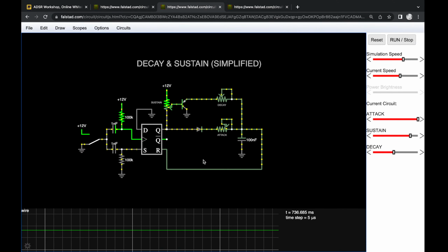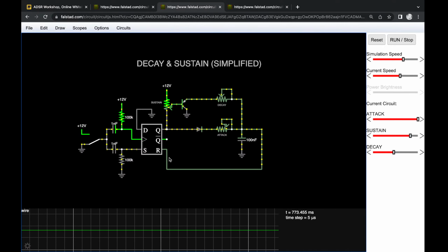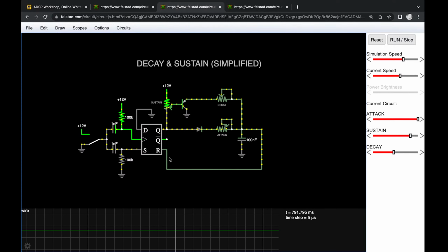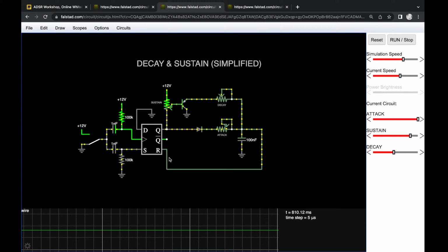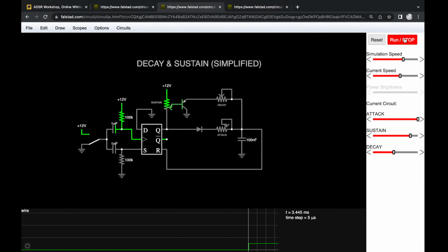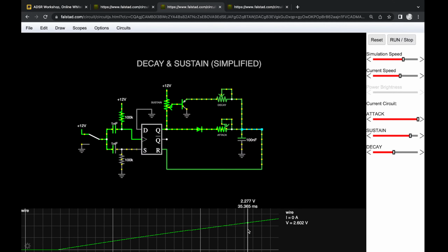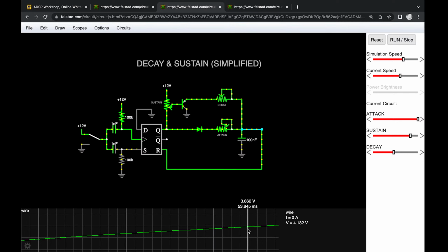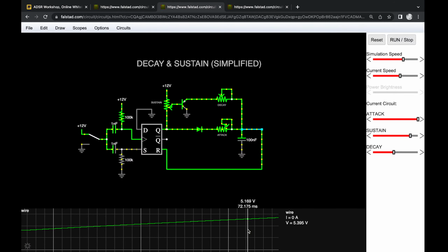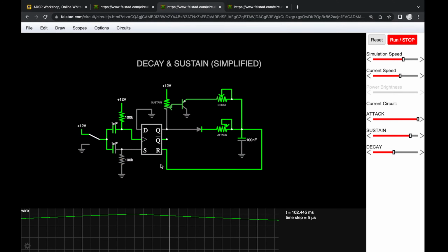Also, I said in the beginning that normally a Eurorack ADSR will peak at around 8 volts. So we should make sure that it does that, because at the moment our envelope peaks at 6 volts. If we try this again, boom, yes, it's 6 volts. That's when the reset input triggers.